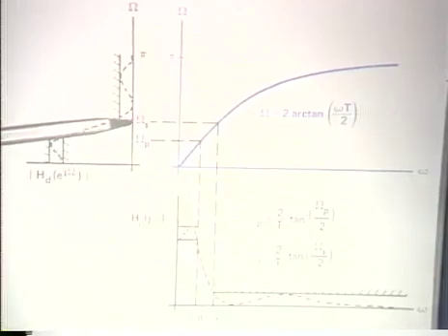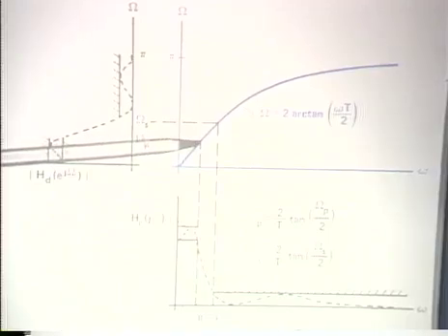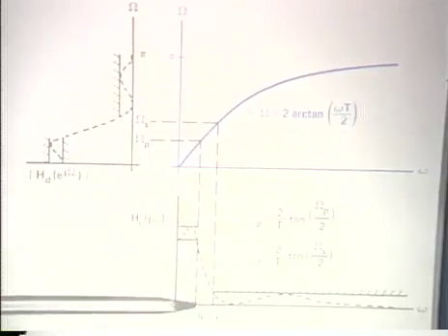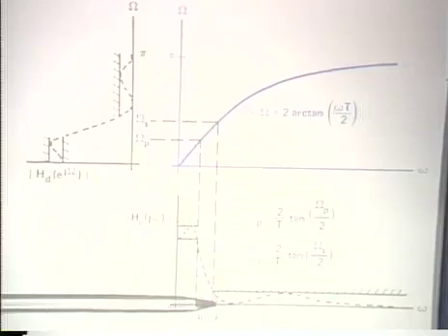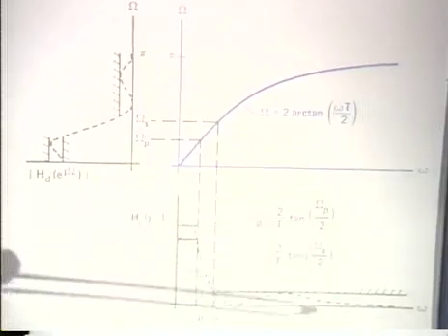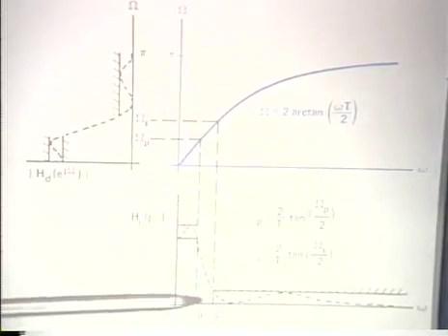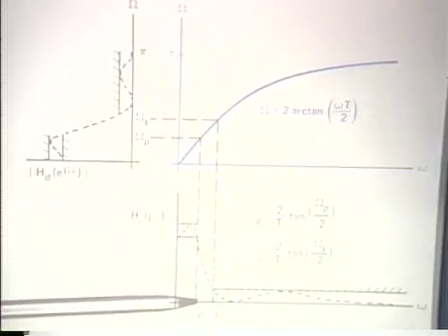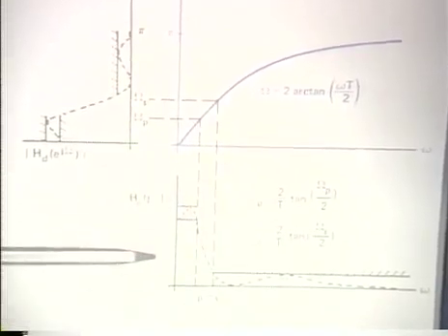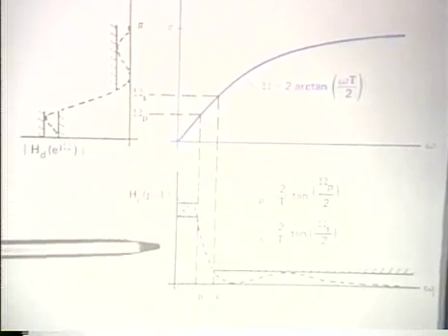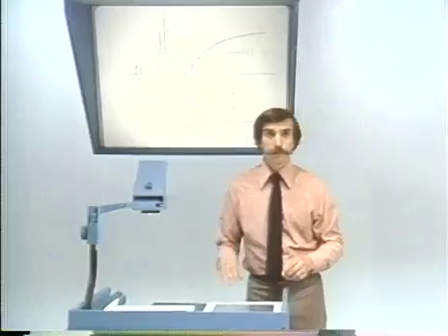The design procedure would then correspond to mapping those frequencies to the corresponding continuous time frequencies, designing the continuous time filter to meet the specifications based on those critical frequencies, then taking the continuous time design and mapping it back to a discrete time filter through the bilinear transformation.